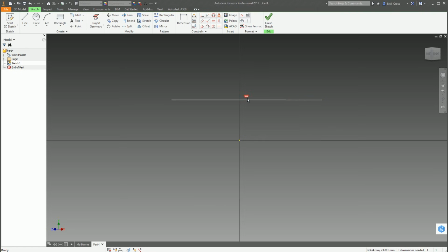So when I click the line, you can see the glyph there. That's letting you know that that line is forced horizontal by a horizontal 2D constraint. So if I grab the endpoint of this line and move it around, I can put the mouse in circles, it will never, ever, no matter what happens in the life of this line, be anything other than horizontal. And that's the whole point of 2D constraints. That's the whole point of them.